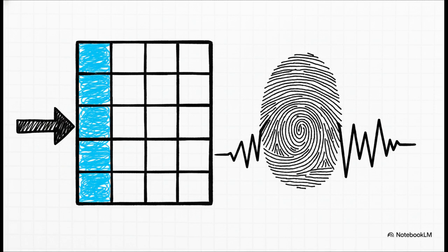For the system to be stable, every single number in that first column must have the exact same sign. If they're all positive, you are safe. But if there's even one sign change, that is the fingerprint of instability. Actually, the specific number of sign changes exactly matches the number of unstable poles lurking over there in the right half plane. Pretty amazing, right?